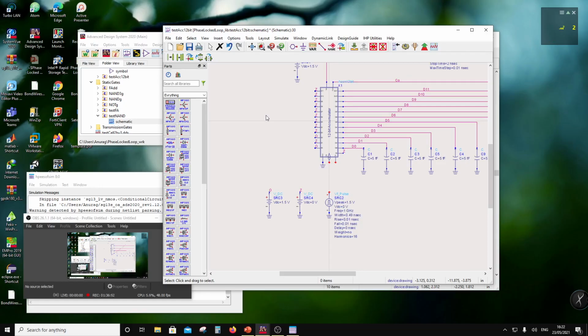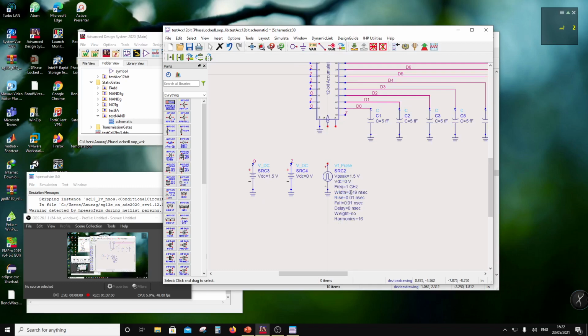So this is that, and I am going to put in a cycle. If this is going to be 100 megahertz, for example, then its time period is going to be 10 nanoseconds, and then the width is going to be 5 nanoseconds. So I would do a 499. So that's a 5 nanosecond. So that's driven at 100 megahertz.